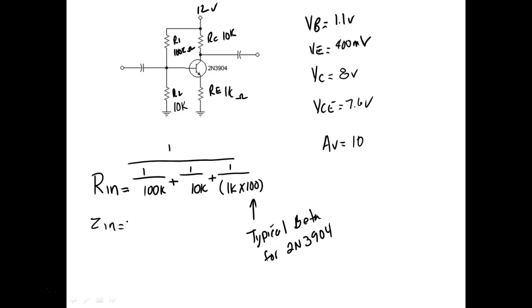We're ignoring the capacitor, and this is what the engineer does. They size the capacitor so that at the frequency in question, we can ignore it. So if this is 100 microfarad, which is what I have, then X of C would be equal to 1 over, let's say 30 hertz. What reactance would it have at 30 hertz?